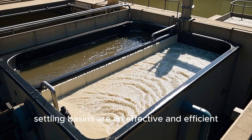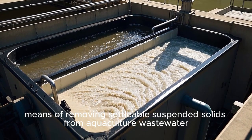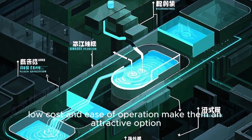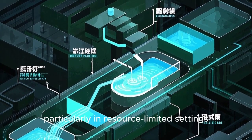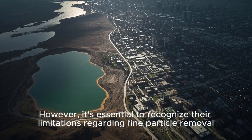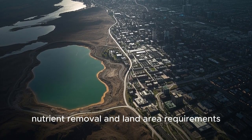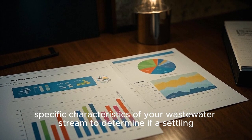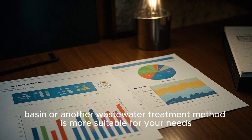So, in summary, settling basins are an effective and efficient means of removing settleable suspended solids from aquaculture wastewater. Their simplicity, low cost, and ease of operation make them an attractive option, particularly in resource-limited settings. However, it's essential to recognize their limitations regarding fine particle removal, nutrient removal, and land area requirements. Carefully consider these factors and the specific characteristics of your wastewater stream to determine if a settling basin or another wastewater treatment method is more suitable for your needs.